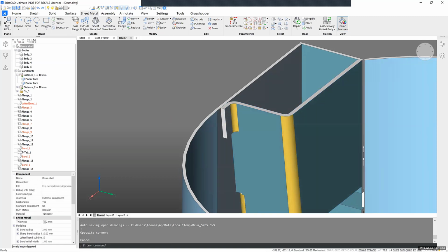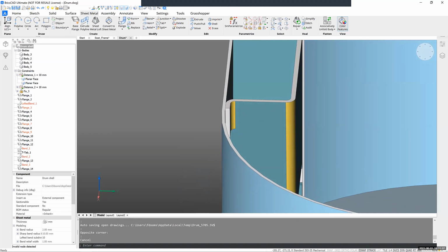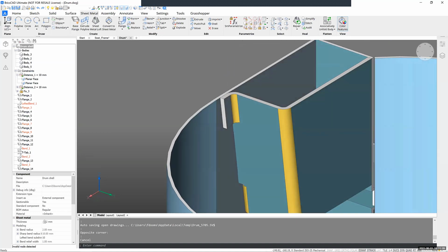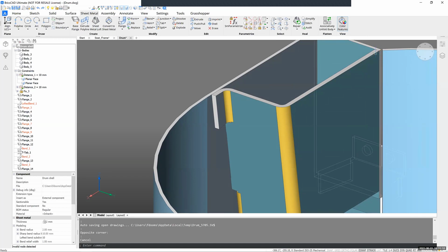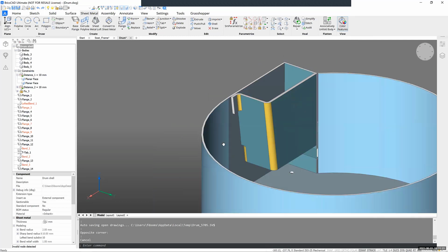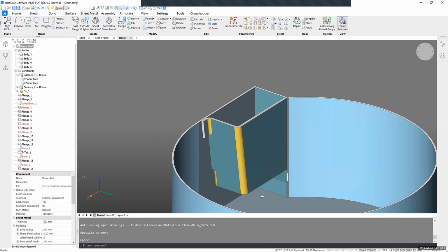And it's respected the design intent again. This is still nicely touching. This is still nicely touching. My corners are still similar. This will still be 12 long. So it's as I wanted. That's how easily you can change the thickness of a part of your sheet metal. So just go to the body, put it on context for solid, and change the thickness.